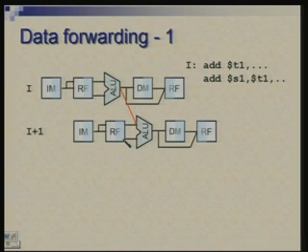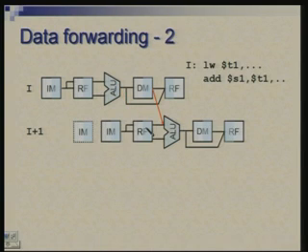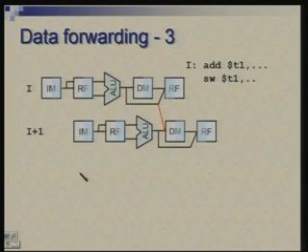There are many other possibilities, and in a subsequent slide let me quickly show other possibilities. If the first instruction is load and the next instruction is, let us say, add, load instruction has the required value available only after the memory cycle. So, here we are forwarding from this memory cycle, from data memory output to ALU input, and here you need to introduce one delay. Okay, but it is still better than having two delays. We have not eliminated the delays, but we have reduced the delays.